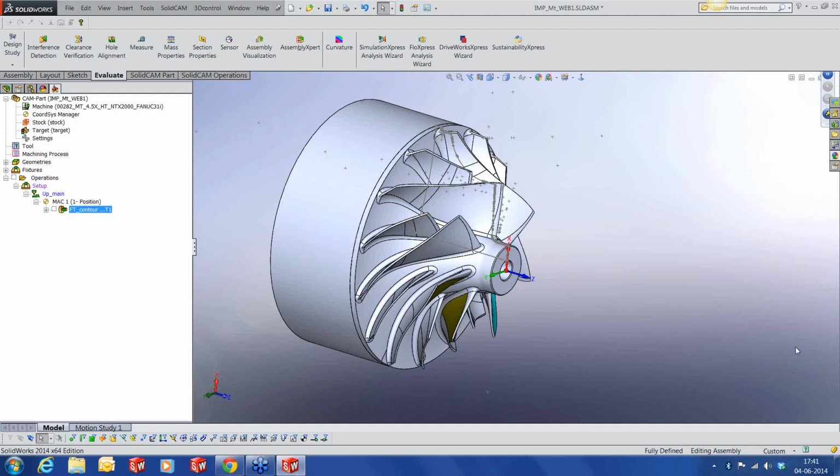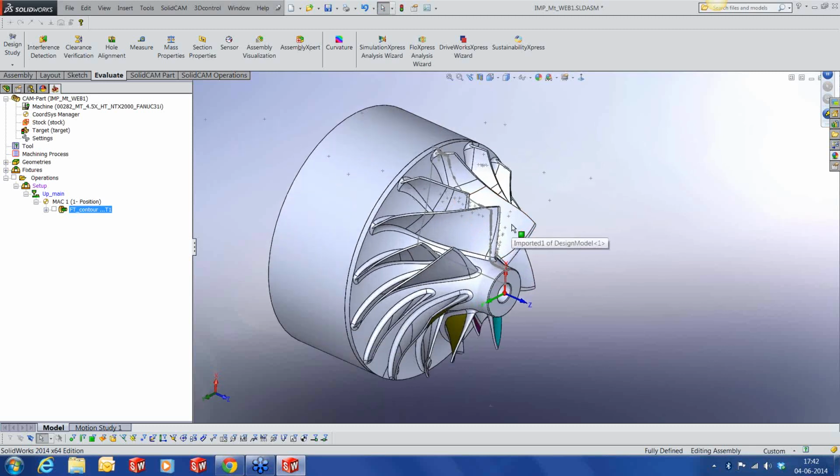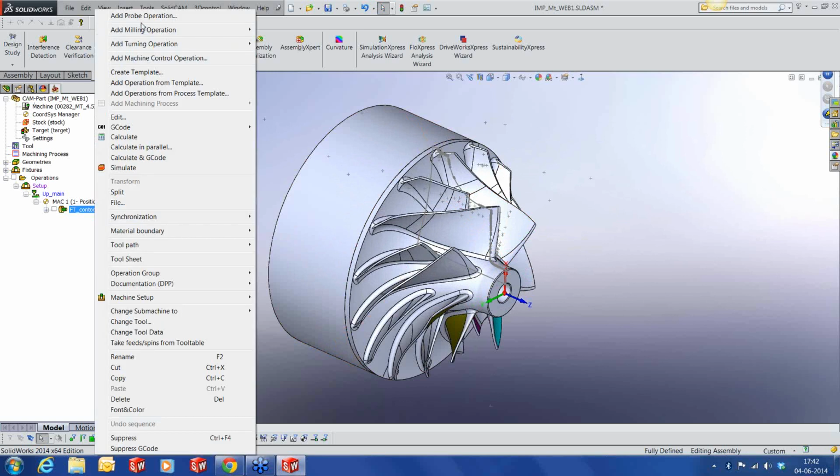First advantage is that the material removal becomes double. The speed of material removal is just doubled because you have two depths of cut being taken at the same time. The other main important thing is our cutting is more balanced in the sense that we have got forces acting on from both the sides, so the cutting becomes much more stable. Right, so let's now run the roughing. Let me add from the turning operation balanced rough.